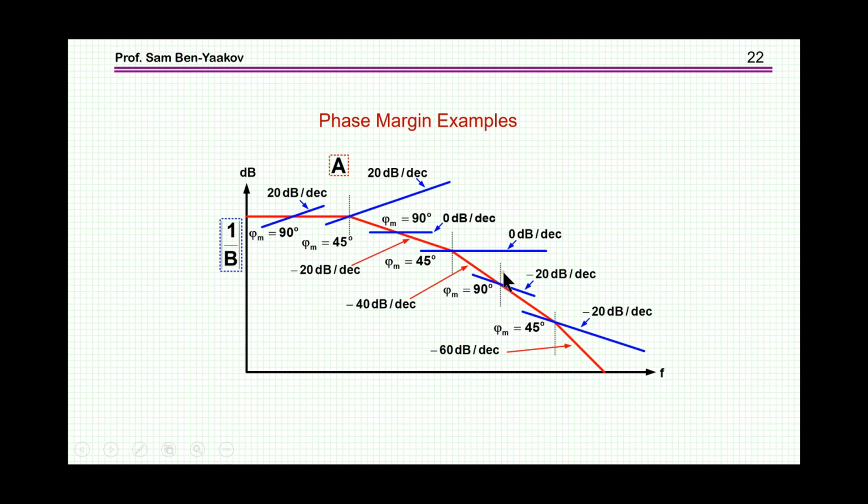So what is really happening is I'm accumulating a lot of phase delay in the system, but I'm now providing a controller with a phase advance, because 1 over beta goes down, then beta itself is going up, which means it's a 0, and I'm adding now a phase rather than a delay, so therefore I can stabilize the system. And then again, if there is a breakpoint and I'm going through the breakpoint, the phase margin will be 45. So this is really very simple.